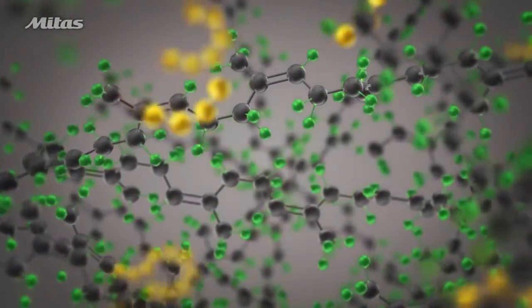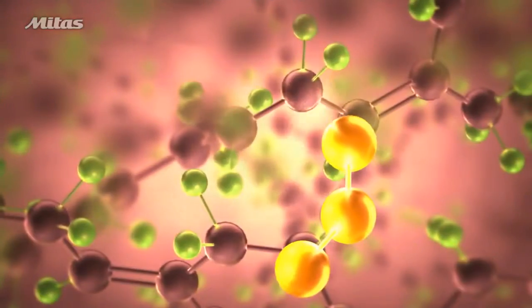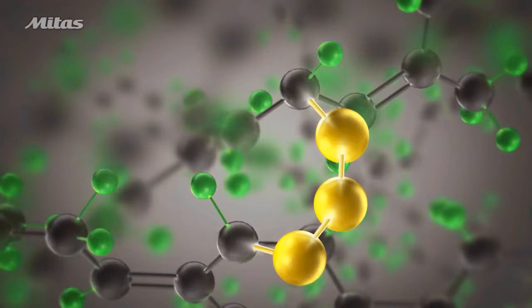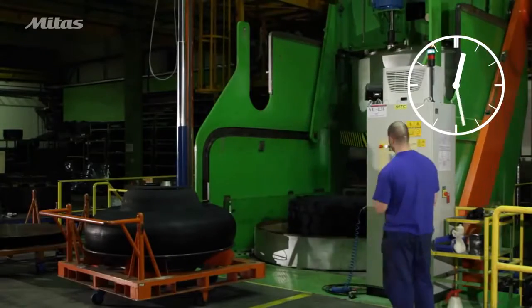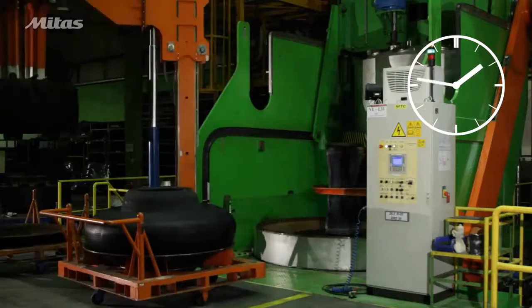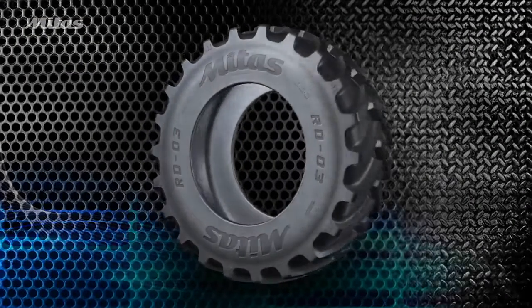This is the basic element of natural rubber molecule. It's a polymer. During vulcanization, these polymers are linked by sulfur. This changes the molecular structure into a three-dimensional pattern of interlinked polymers. The vulcanization of a passenger car tire takes only a few minutes. For an agricultural tire, this process can take up to 2 hours. This is a final product, a cured tire.